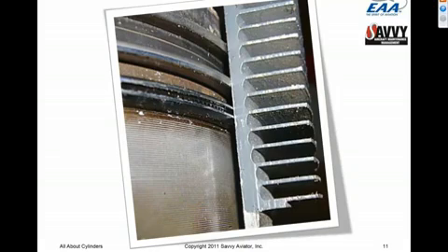But when the cylinder is cool, the fit between the piston and the cylinder is extremely sloppy, and the rings have to make up a big gap. This is something that we have to deal with when we're first starting the engine, and it's something we have to deal with, for example, during compression checks, which I'm going to talk about in a minute. But it's not a factor when the engine is running and up to temperature, because the fit between the piston and the cylinder is quite snug when everything is up to full operating temperature.